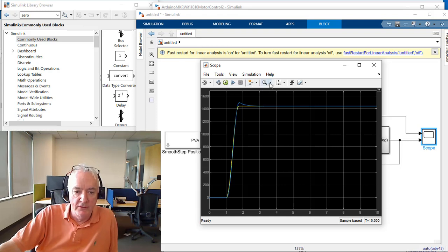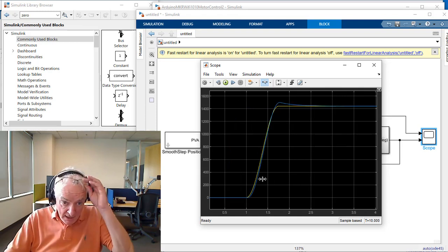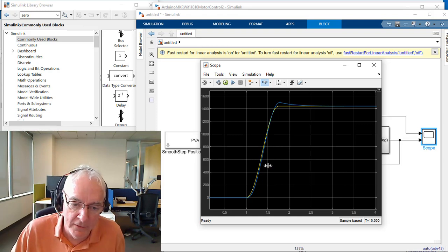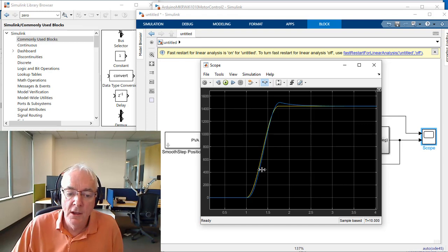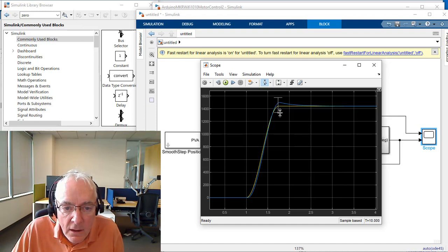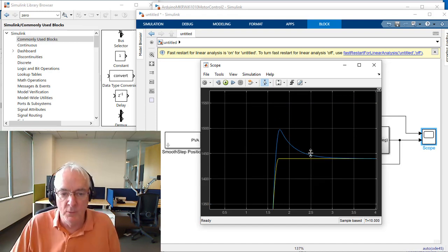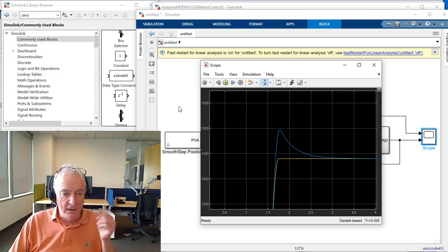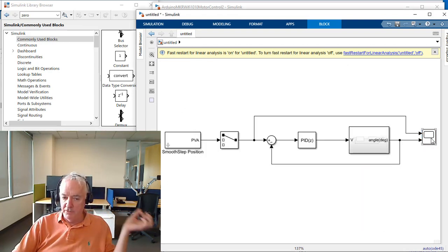And I find this really interesting. I'm going to compress this and look at it from that scale. What I think is really impressive is that it looks, again, very close to what we saw in our hardware test, where all of a sudden there's much more noticeable lag in the response, and we're definitely seeing that down here. And then there was an overshoot. I recall our overshoot being about 80 degrees in the first demo, and this one's about 60 degrees. So it's not perfect, but it's awfully close.